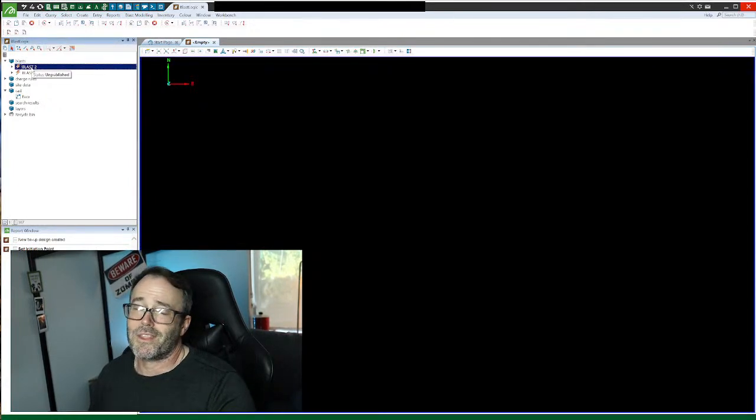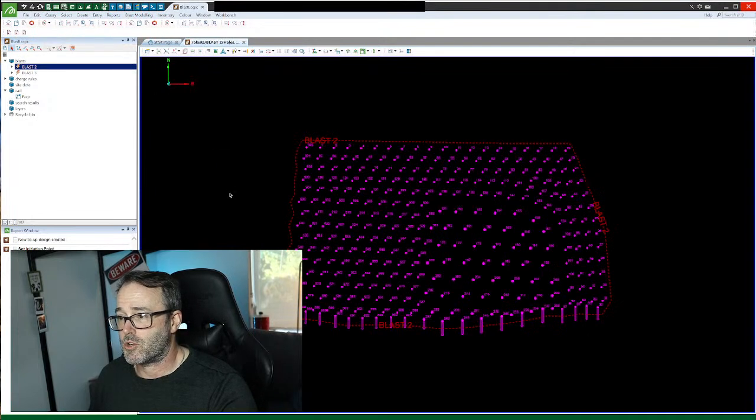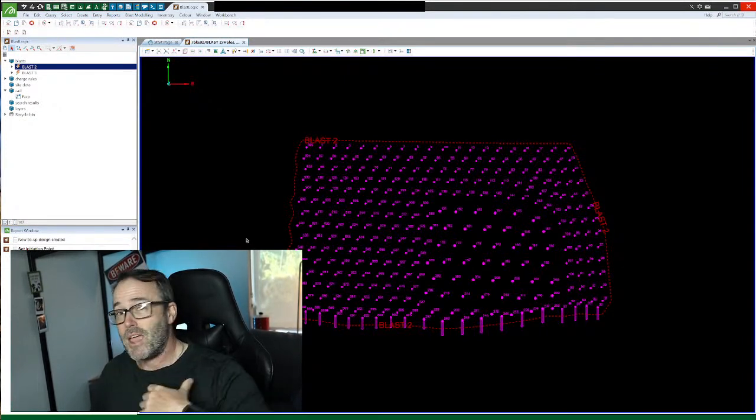And one of the things that always gets people with Blastlogic is it's a middle mouse button drag to drag it into the screen. I know people often get a bit upset about that and want it the left mouse button, and I would like it the left mouse button, so if anyone's listening, that'd be great. But it is a middle mouse button to drag it in.